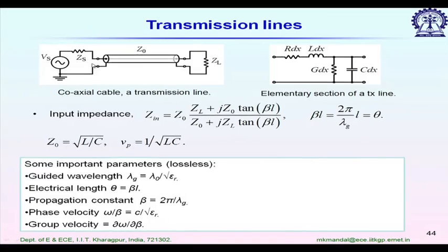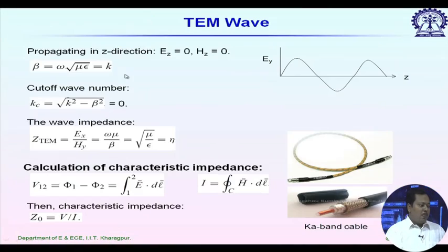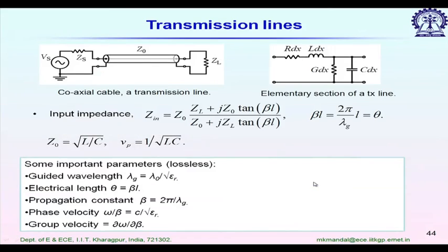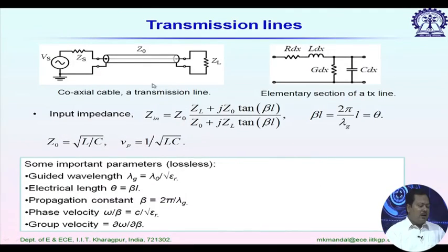So let us take one example here. It shows the coaxial cable, which comes in different forms. It is very popular at microwave frequencies. At millimeter wave frequencies it becomes lossy, but since it has the advantage that we can easily turn it and also twist it, it is usually used with measuring instruments. So this transverse electromagnetic wave, any guiding structure that is supporting it, can be represented by a transmission line.